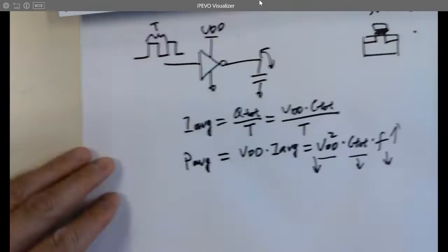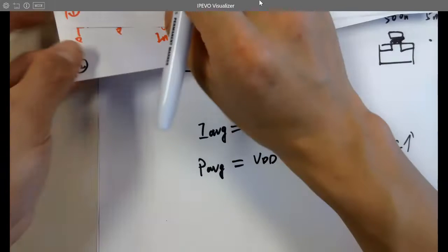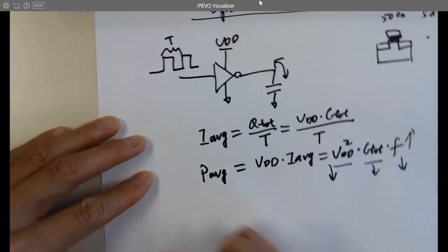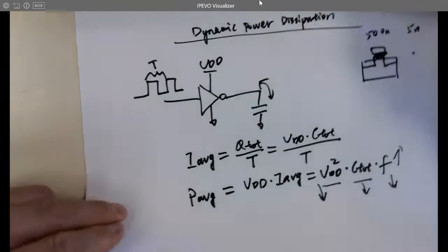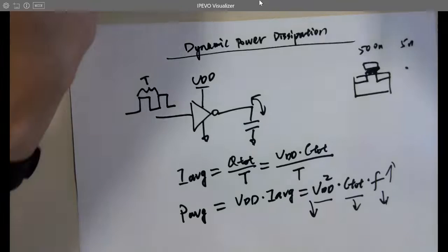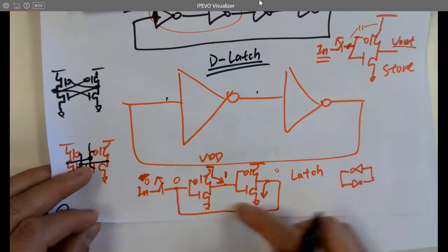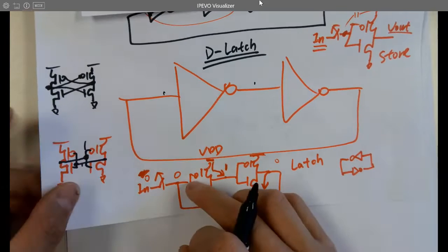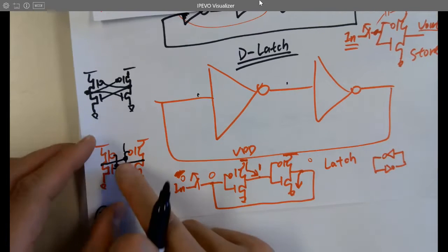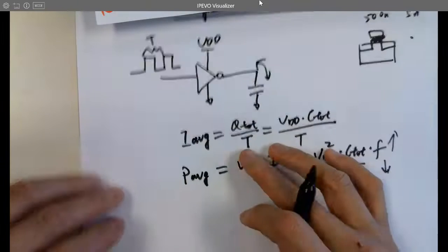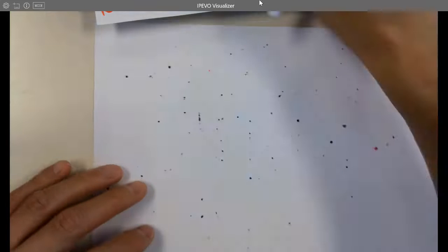I'm going to show you a different structure of the D latch. The D latch I just showed you is a fundamental component of the clock, and it's being used for the D flip-flop. It's one problem in homework 10. So this is a latch, okay? But if you want to make it into a D flip-flop, you have to introduce transmission gates in there.